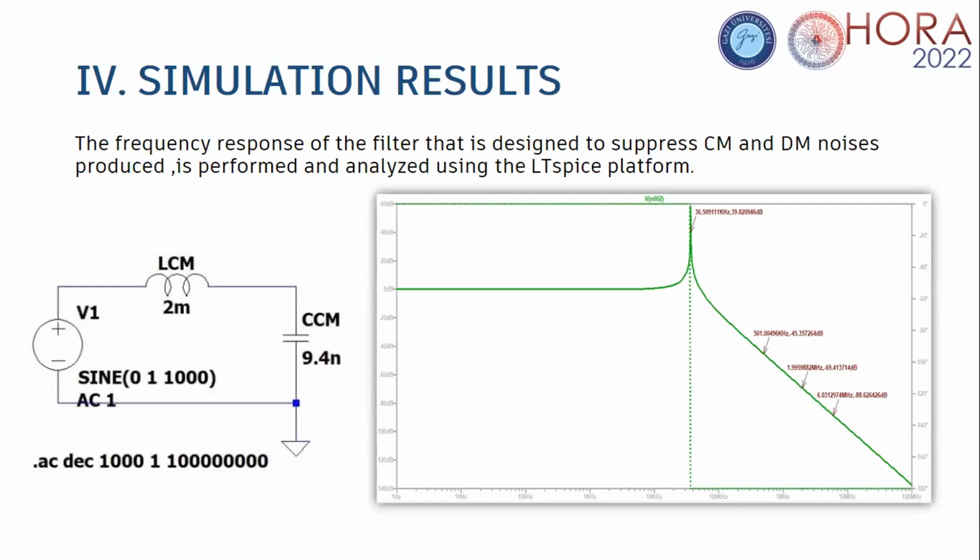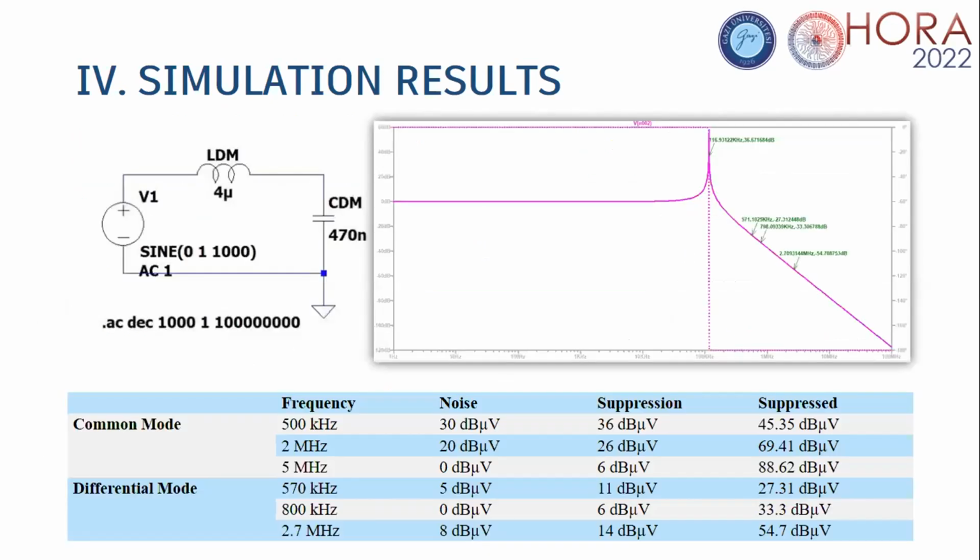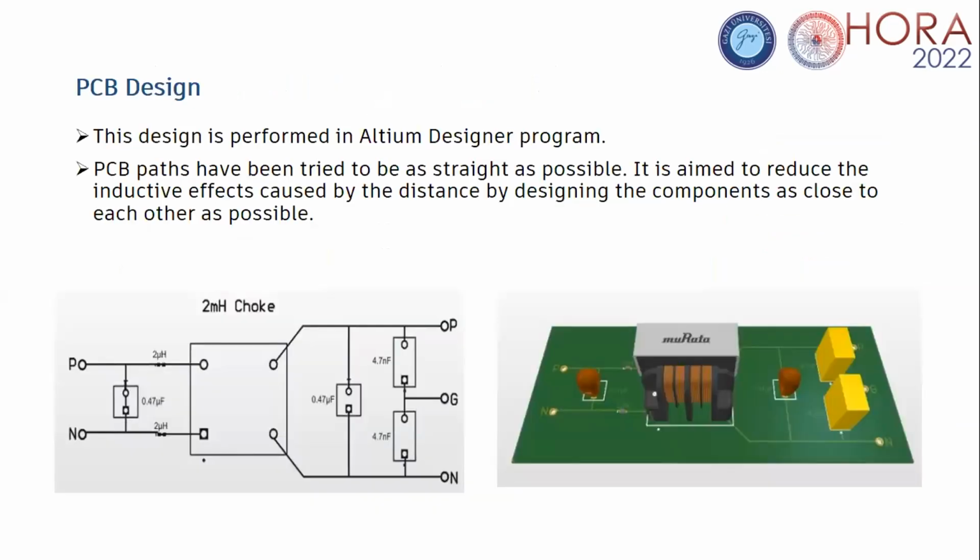Then we simulated equivalent common mode and differential mode circuits in the LTspice program. Here is the common mode circuit simulation and the differential mode circuit simulation. We examined the frequency responses of these circuits and recorded the suppression values at the same sample frequencies in a table. After the circuit design phase, it was time for PCB design.